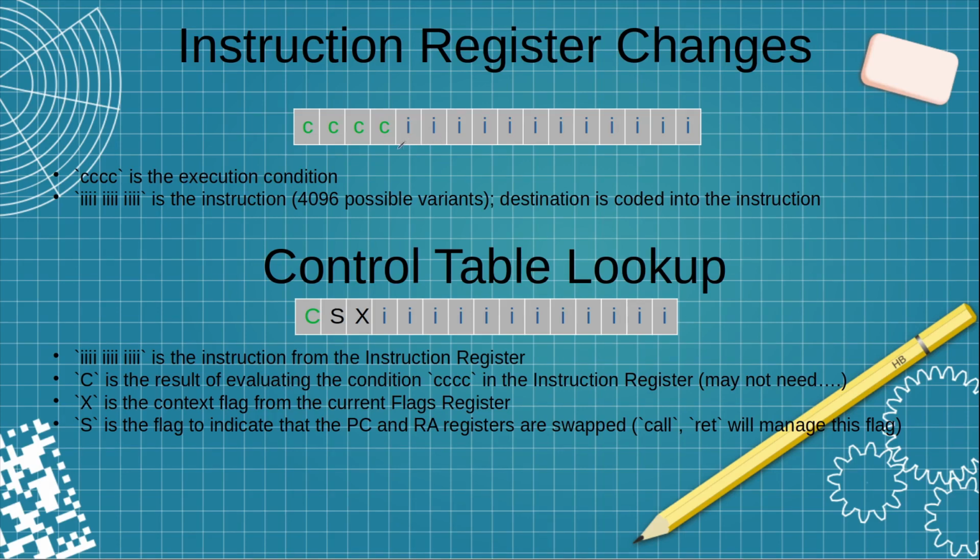What I had intended was for these 8 bits to indicate what instruction was going to be looked up in the control table. And I had several additional bits that were unused up at this end of the control table lookup. Well, I've since decided that 256 instructions just aren't going to cut it, because some things are going to assert onto the main bus, and those will be by register that are being handled, and some things just aren't going to be able to do that. And 256 instructions were going to leave me a little bit short.